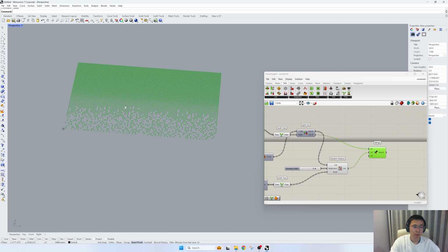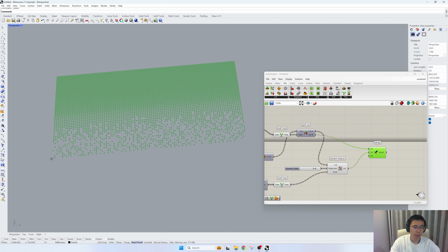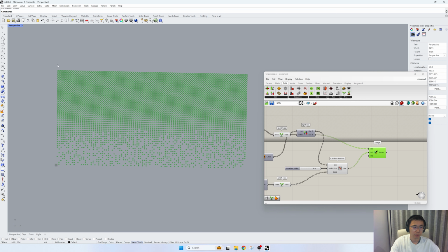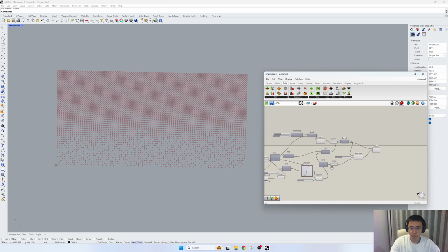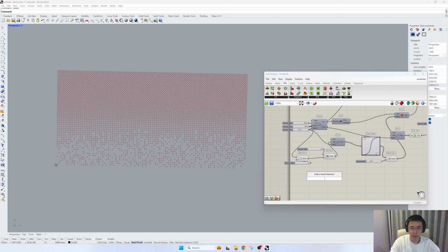For practice, you can actually send these curves to the manufacturer. They can use these curves as CAD to cut the panel. But for rendering purposes, we need to change this pattern to a surface. So at first, we need to create a rectangle as a basic surface.